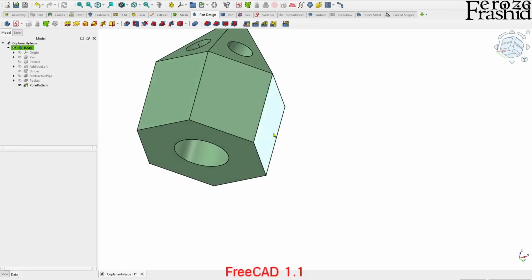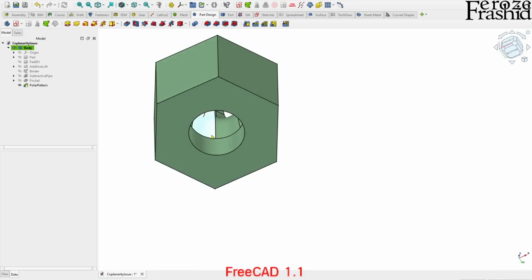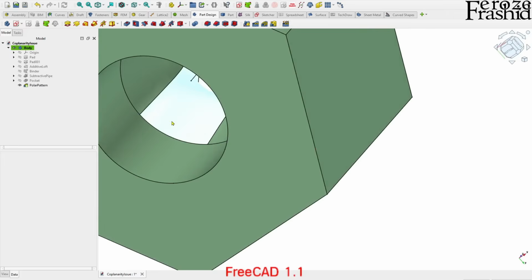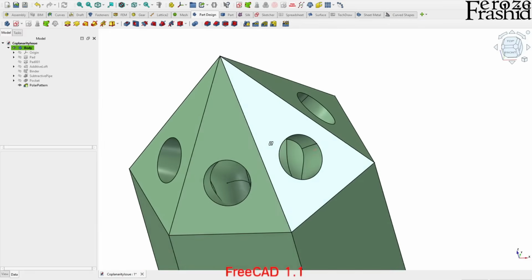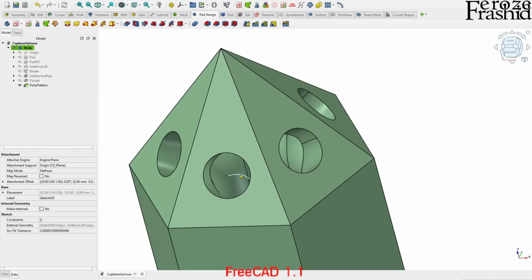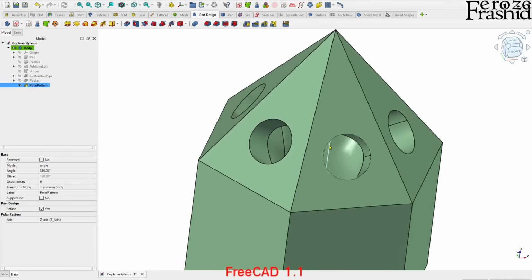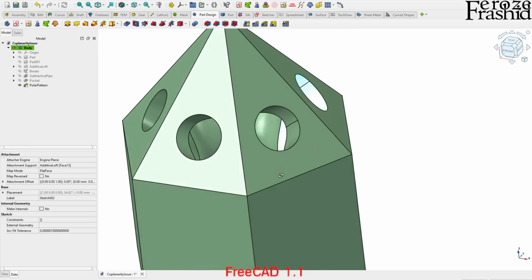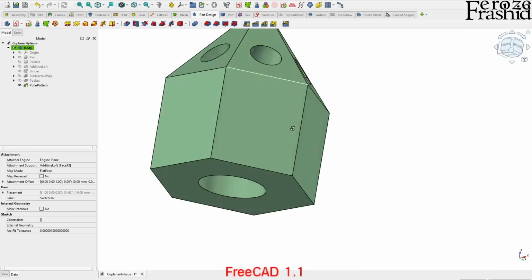So the coplanarity issue has been taken completely out of the equation. This is the area, the lower end of the pipe, that was causing the coplanarity issue, overlapping with each other, and now it's not. Now we took it out of the equation. So that's one way to handle coplanarity issues: not to cause a coplanarity issue to begin with. So sometimes we have to be calculative on how we think our model should work and how we should build it up from the ground.